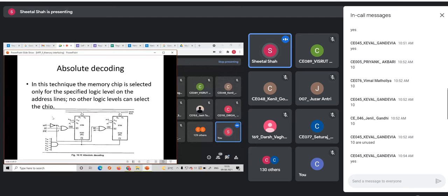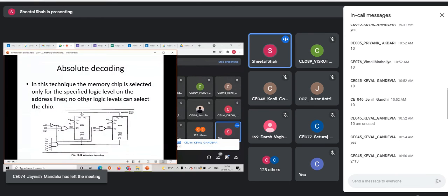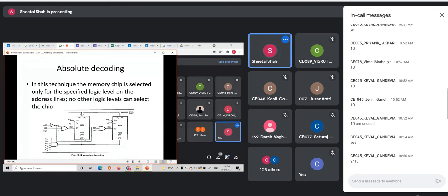You can see in this example, we are having two ROM ICs, and here it is using address lines 1 to 13. So what would be the capacity if it uses 13 address lines? 2 raised to 13 is equivalent to 8K. So the capacity of this IC is 8K, and you can see it is written here ROM 8K. Here also it is a ROM 8K.